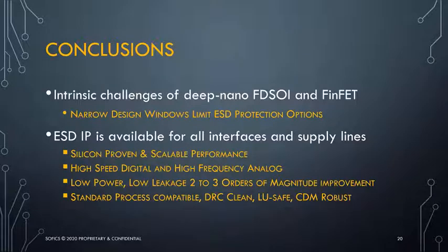As a conclusion, I would like to summarize what I've talked to you about. We've talked about the intrinsic challenges of deep nano FDSOI and FinFET technologies, basically addressing the narrow design windows that limits the ESD protection options. I've also demonstrated with data that there is IP available for all interfaces and supply lines that are silicon proven and have scalable performance, that can support your high-speed digital or high-frequency analog designs.